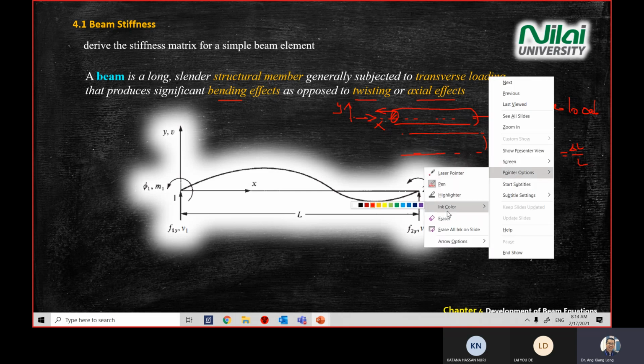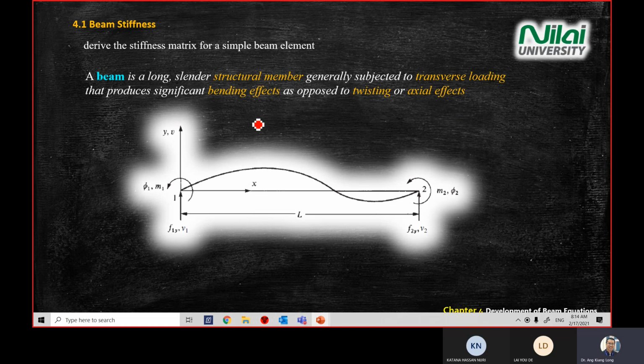So in chapter 4, when you're told to do analysis, we'll only look at 2 effects. Again, we'll look at bending effect and twisting effect. If you look at the member of the solid line here, this is the beam under the loading scenario. Let's say we have a force support, an F in Y direction. At this point, you should already understand the notation f1y.